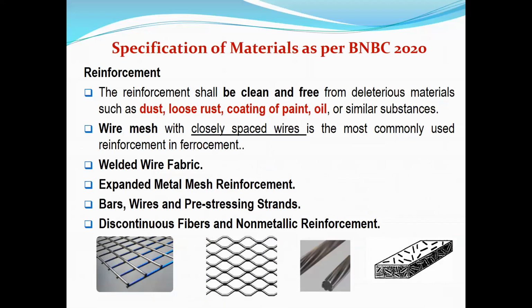In terms of reinforcement, the reinforcement should be clean and free from deleterious or harmful materials like dust, loose rust, coating of paint, oil, or similar substances. Wire mesh, so you can see the wire mesh. Actually, this is the wire mesh, with closely spaced wires, which is the most commonly used reinforcement for ferrocement.